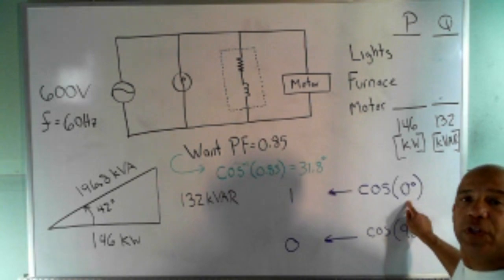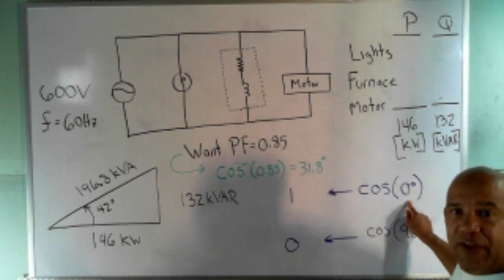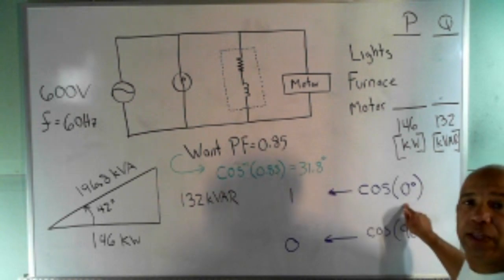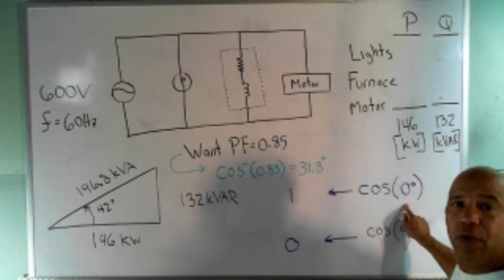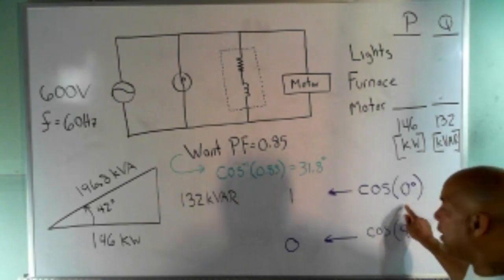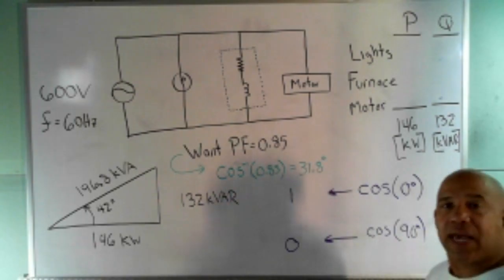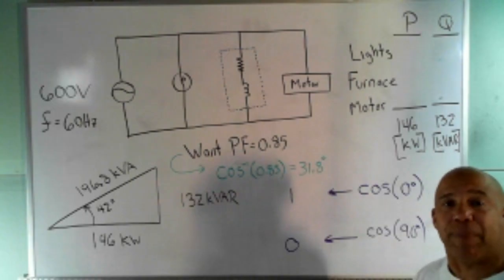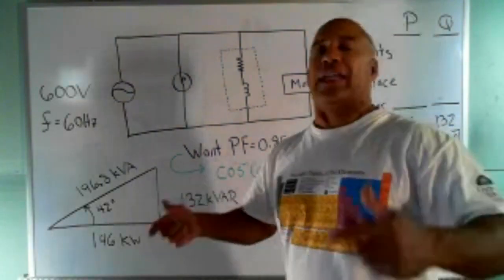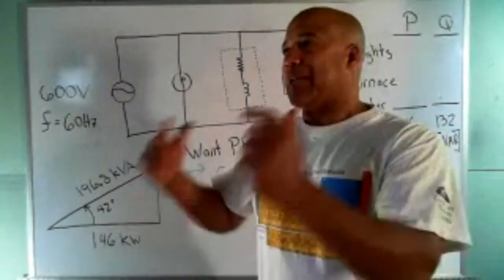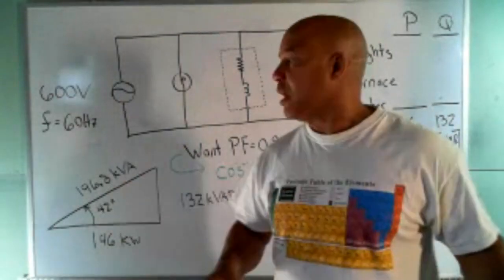The voltage across the resistor is in phase with the current through it. This is the phase angle between those two quantities, and it's a 0 when you have a resistive load. When is it 90? When you have reactive loads. Now, I mentioned a long time ago that resistive power is the only kind of power that can do work, because to do work, you have to convert power from one thing to another, from electrical energy to heat, from something to something else.